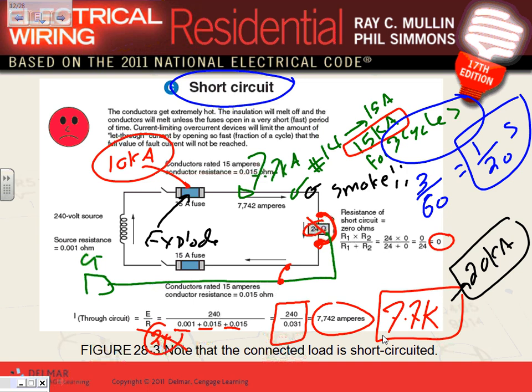What's the difference? The ground fault is not as high as the three-phase. It's going to be less than the three-phase. So if you have a ground fault like this, the current that you might encounter here could be 4,000 amp. Now I'm going to look at Nick and tell you, Nick, if it's a 4,000 amp ground fault and a 7.7 short circuit, can this conductor under these circumstances, 15K and 10K, handle the 4K? Yeah, if they can handle 7.7K, they can handle 4K. That's what the ground fault is, a fault that is less damaging than the short circuit.